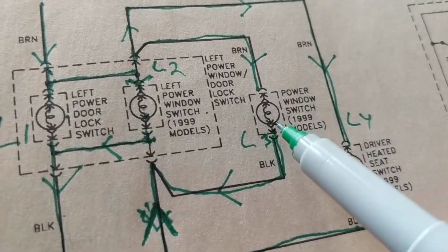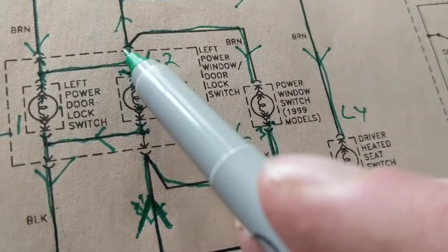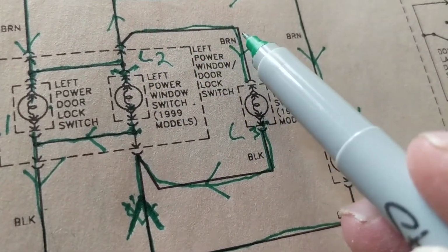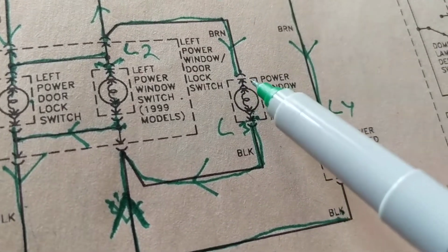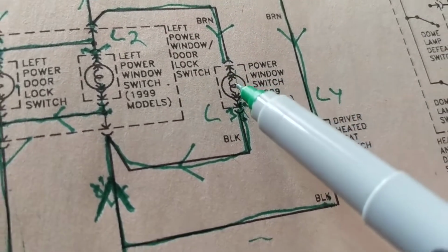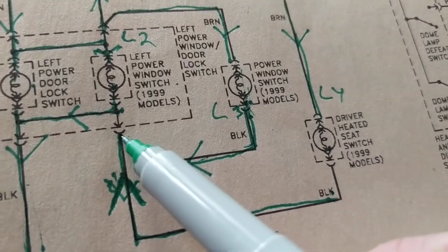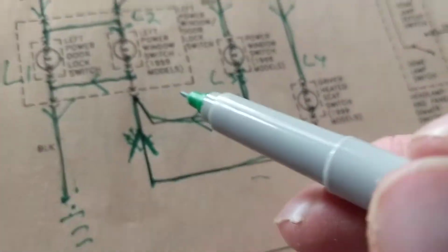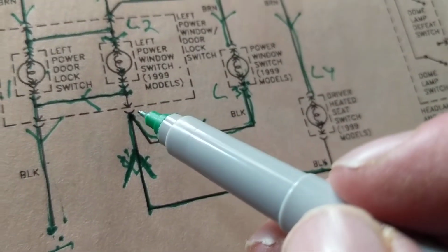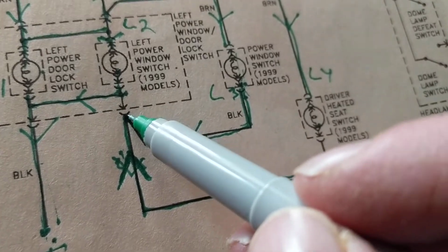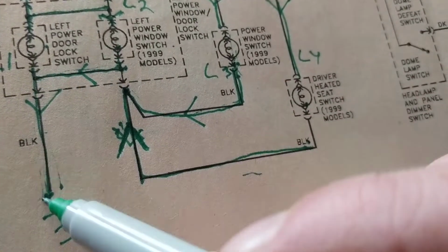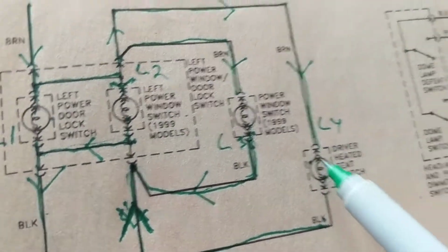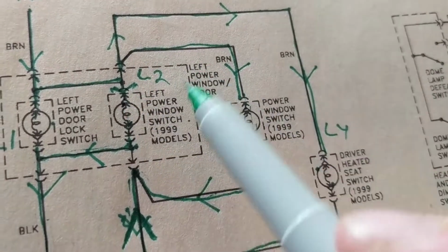What about these? How is this going to be lit? Current comes to this point, or the splice, or the node, comes over here and says, okay, I'm going to go through this brown wire. I'm going to light him up when he activates the switch. The black, and now I'm going to come out here. Where is he going to go again? We just said a rule. You take the least amount of resistance. Where is the least amount of resistance? Right here. Back over here. This is the ground. He's not going to go back up here. If it goes over here, it's going to go through this one or this one. No, you don't do that.